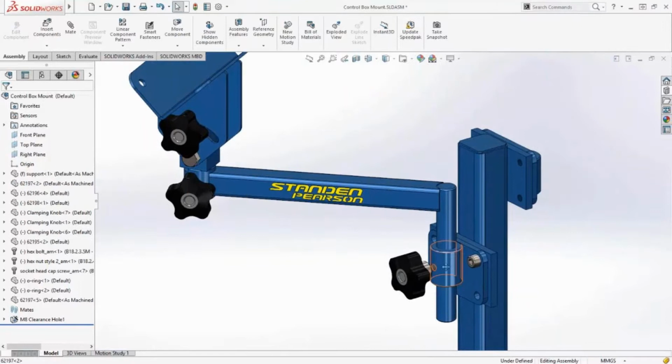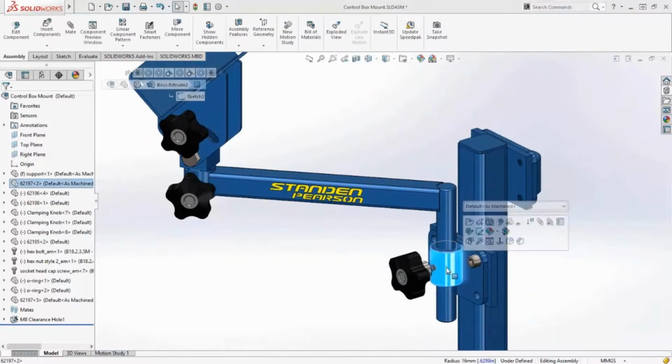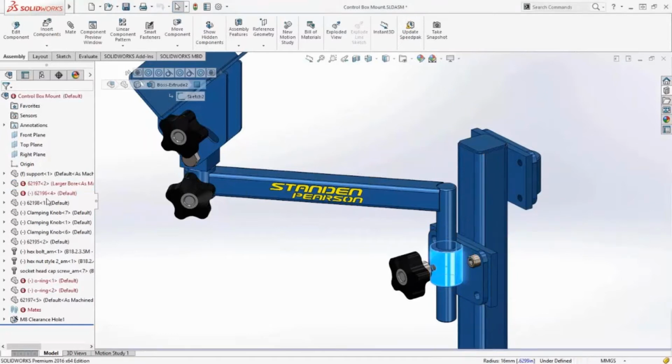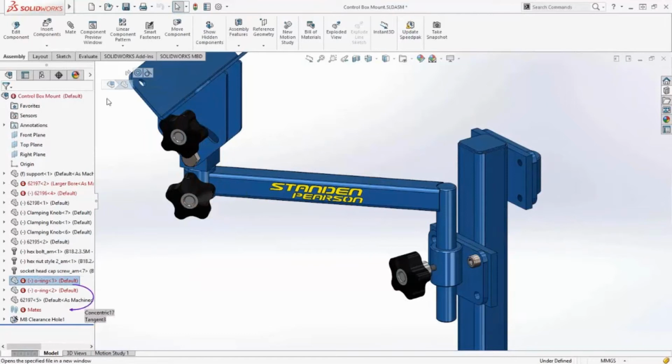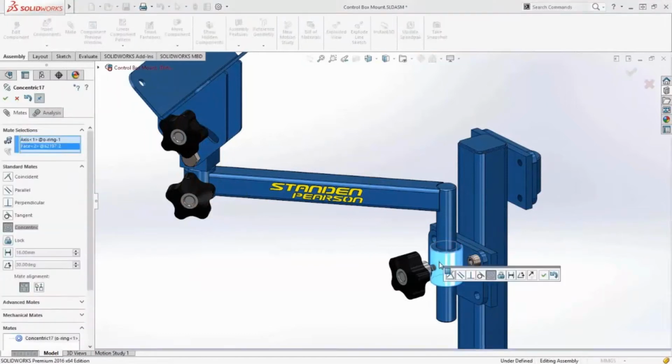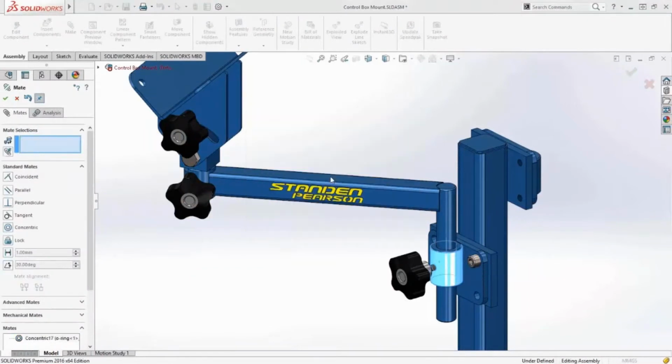Now, if you guys can remember back in SOLIDWORKS 2015, we introduced the ability to replace a lost mate reference that was used by multiple components. For instance, when this bracket was bored out, the face used for mating was removed, resulting in failed mates. After editing one of those mates to the part, you were then prompted to repair all the other mates to that face.